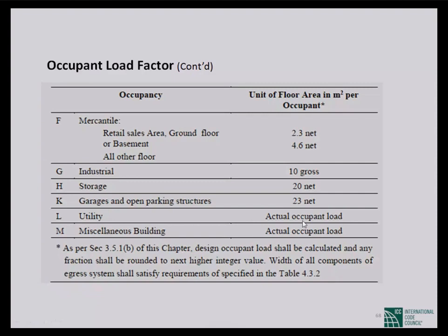That is due to human comfort. You need air per person of 10 meter cube. If I divide by the height of the building, it is 3.6 for industry. It becomes about 2.6, 2.8. As per labor law, it is 2.8, and that is followed by garments factories at this moment.